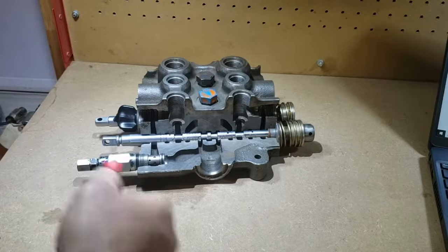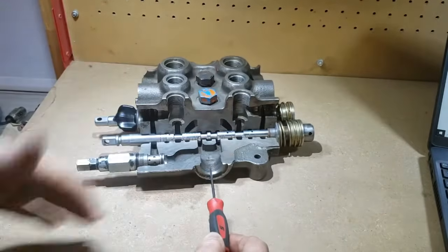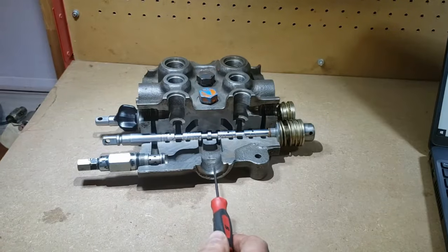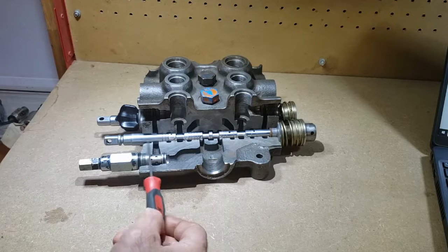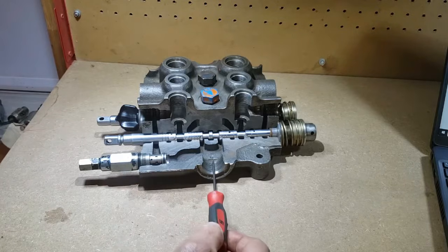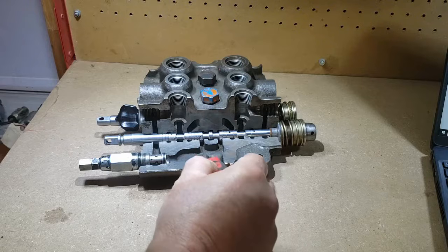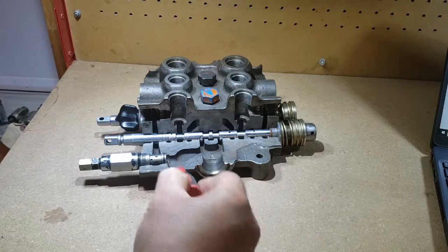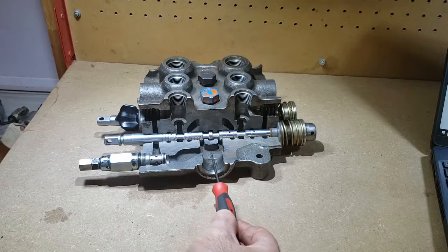So starting back here where the oil comes in from the pump, again, this valve's been machined open on the supply end here where the lift spool sits. So we can see how the casting is made by cutting it open. Where the pump supplies oil here, we can see we've got a fairly big open chamber where it can go to the main relief valve. Main relief valve always has access to pump supply pressure.